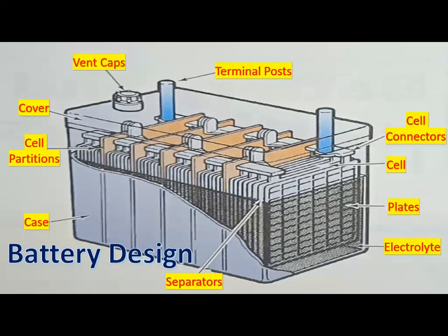On top terminal batteries, large round terminal posts extend through the top of the battery. The positive post is larger than the negative post. These terminal posts are sealed into the battery cover to prevent electrolyte leakage around the post. Positive or negative is stamped on the battery cover beside the proper terminal post. The battery cable ends are clamped to the terminal post. On side terminal batteries, the battery terminals are threaded and the cables are bolted to the terminals.